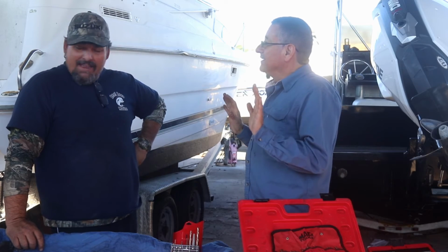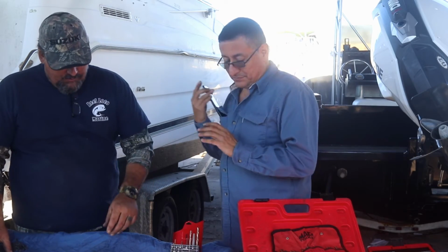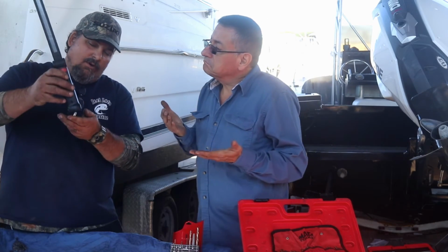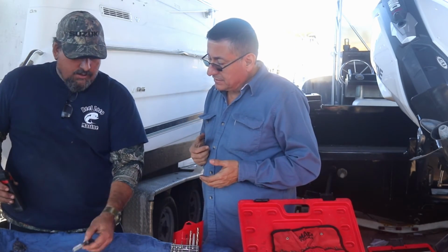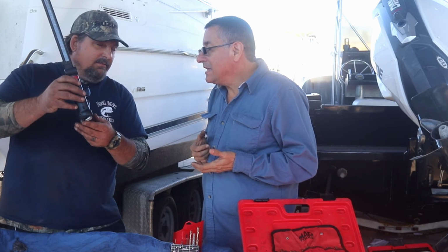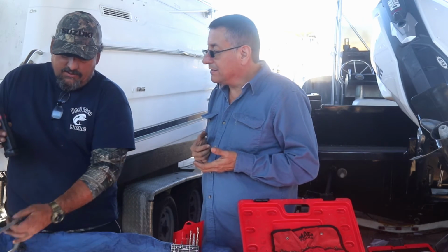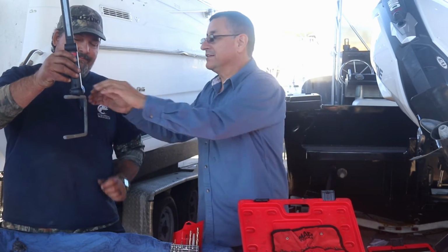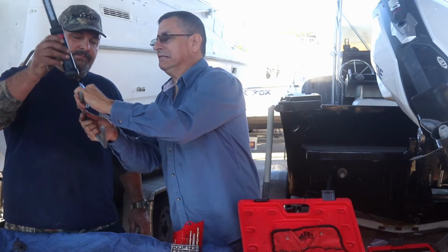The magnet. Magnet's your best friend. So, like this one here is a good stainless steel. It doesn't grab, right? No grab. This one here is somewhat a good stainless steel. A little, okay? And if it's not stainless steel, oh yeah, that's nothing. Look at this, my friends. Externally, it's too hard, no?